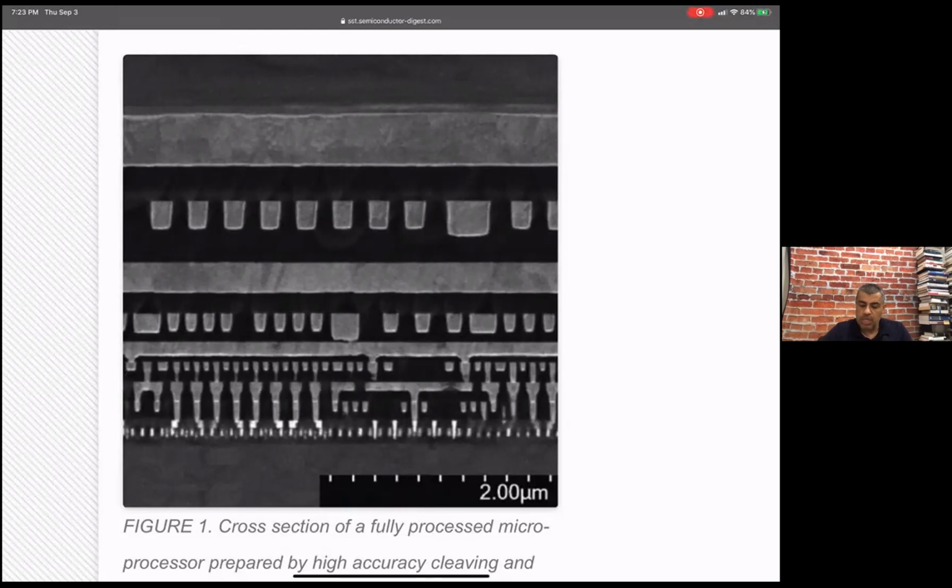So you also see how the metal lines are getting thicker the further they are from the surface of the chip. It's just the way it works for various reasons. It's easier to do that. So the very top metal layers are usually used for power supplies, clocking, those kind of things, because they're thick, you also can't make their details very fine.